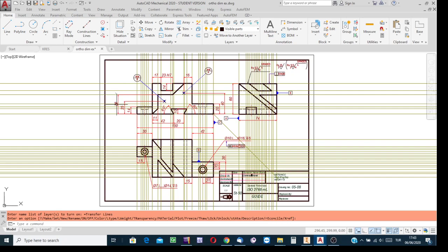Since between the views we have the x, y, z axes, obviously the views must be consistent with each other. While creating the transfer lines, at the intersection of transfer lines we have the images of the characteristic points: terminal points of the straight intersections, center points of the circles, tangent points, etc. On this view and on the adjacent view, on the other side view, they have the same x, y, z coordinate values respectively.